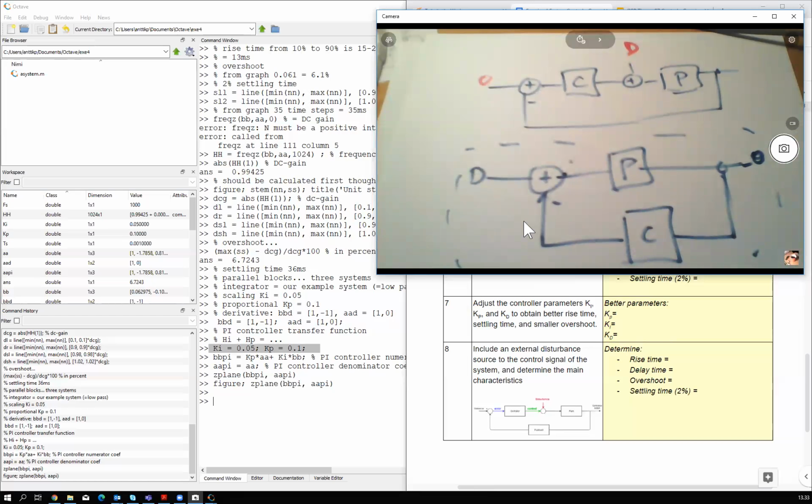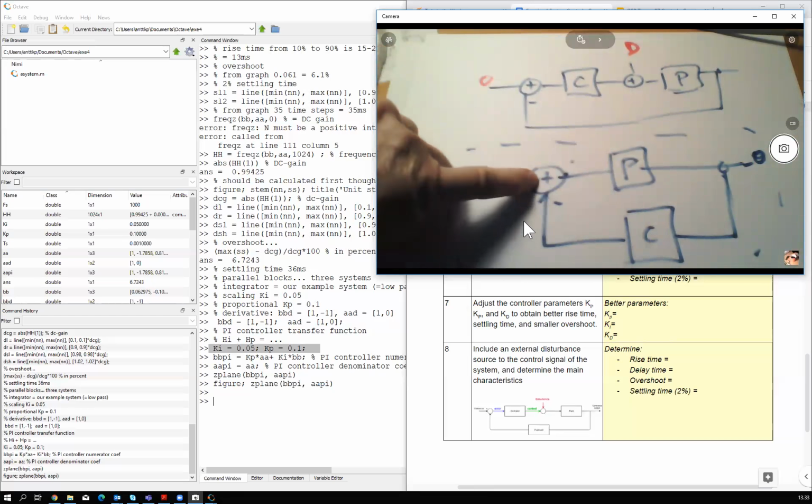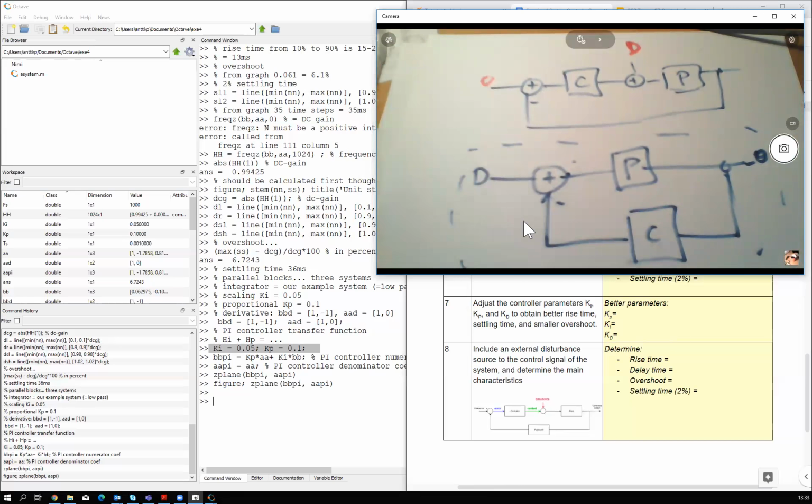and then you can take a look how much an external effect actually disturbs this system. What is the rise time? What is the delay time? What is the overshoot? How fast it settles? So that tells you how well your control loop is actually reducing the effect of external effects, like, on a heating system you have an external heat source in addition to your heater, for example the sun, or on cruise control you have uphill or downhill, or in any engine you have a variable load. That will be your external effect.